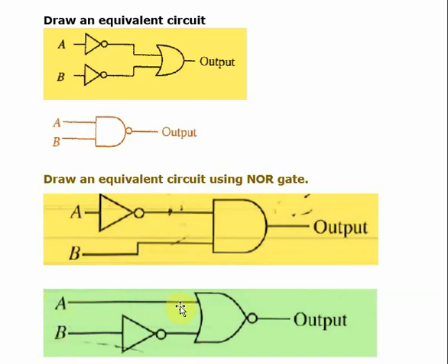You are feeding 1 here, right? To make it 0, the OR gate output should be 1, right? So here this has to become 1. A1 B1, so here becomes 0. So it's 0 and 1, 0 and 1, you will be getting 1. Since it is NOT, again the output will be 0.